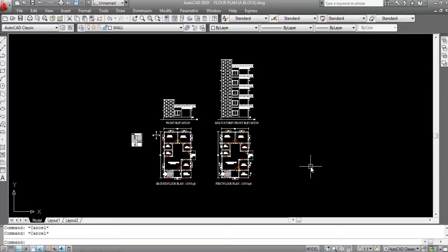So, the necessity of section is to indicate the interior exposed view such as thickness and height of walls, height of doors and windows, foundation of the superstructure wall, thickness of lintels, floor section, parapet and such other details on the basis of which quantity of works are worked out and execution of work is done.